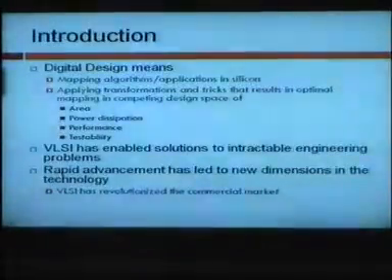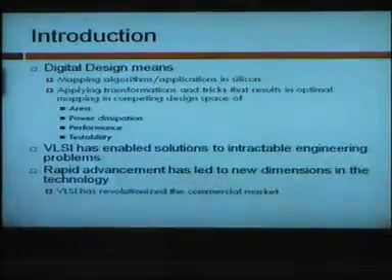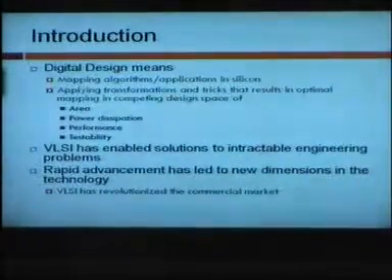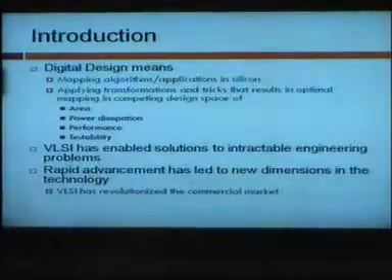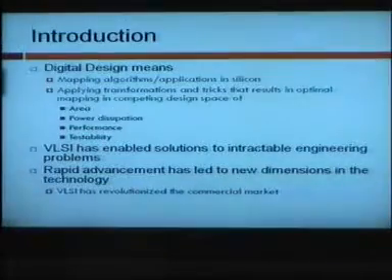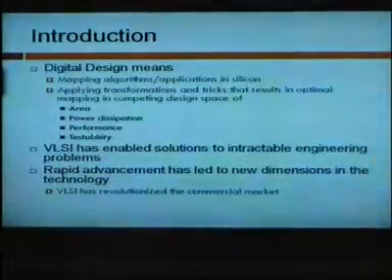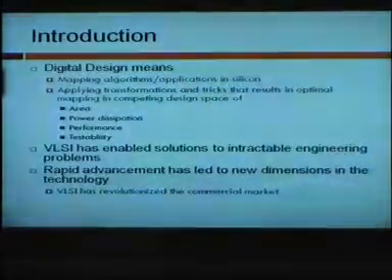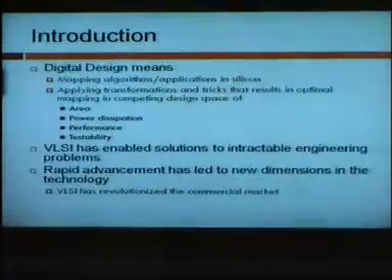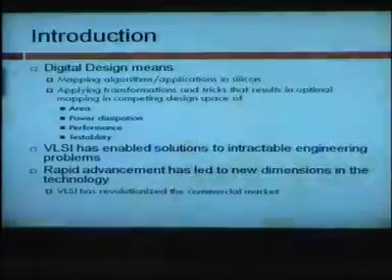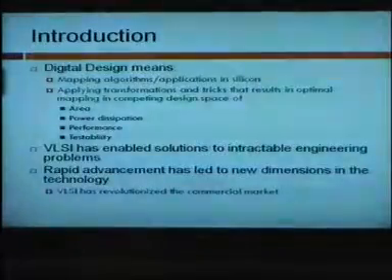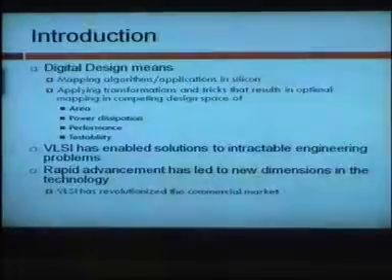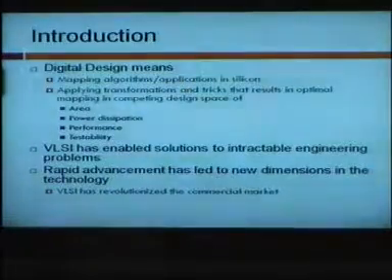Usually designers ignore this very important aspect of digital design: once you are designing, you need to put thought into testing the design, because testing hardware is very difficult. Testing a piece of software is very simple because it's sequential. You can put breakpoints, you can put traces, you can do logs, because it only executes one instruction at a time. In hardware, everything is alive all the time. If there are a million gates, they all are alive all the time. And because they all are alive, it's very difficult to find out where the bug is.